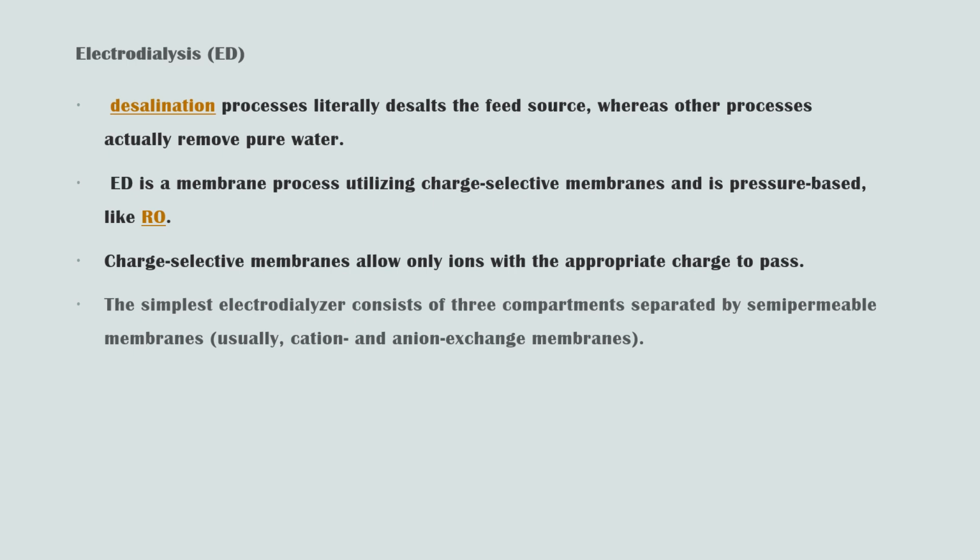Among electrochemical methods of water purification, we can also list various electromembrane technologies in which electrodialysis is very important. Electrodialysis is quite unique among practical desalination processes because it literally desalts the feed source, whereas in other processes, actually water is removed after purification.